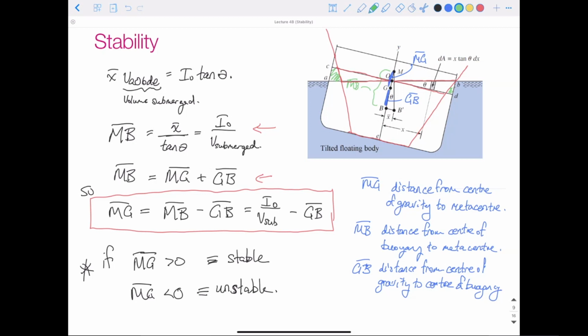So in this case that we drew, because we had just vertical sides of our hull, yeah, it would appear that way. But if we don't have vertical sides to our hull, then that's not necessarily the case. So we can see that the red shape that we just drew, if we don't have vertical sides to our hull, we have a V shape. When we actually tilt it, we have more of the body submerged than we have actually come out of the water. So our center of the submerged volume is going to move more from that center line than if we just had our vertical hull sides. So that's why you see a lot of ship design has that V shape. It's a more stable shape in the water.